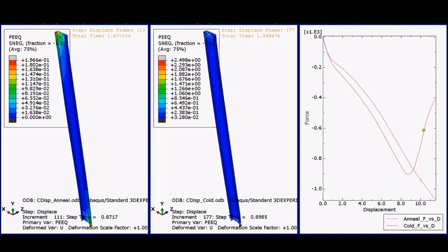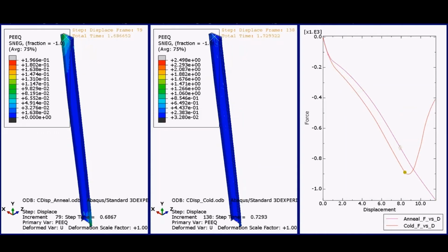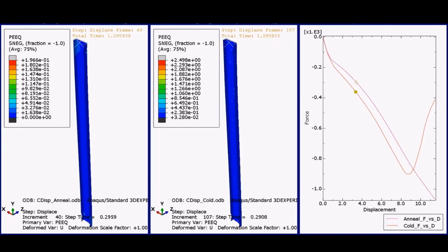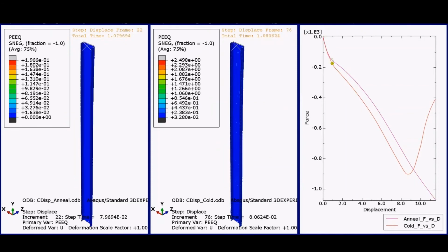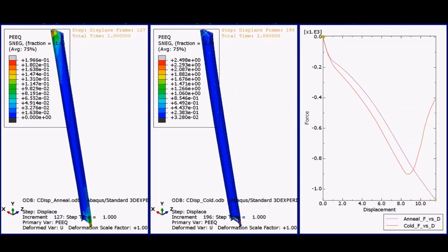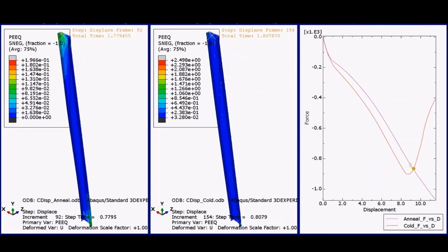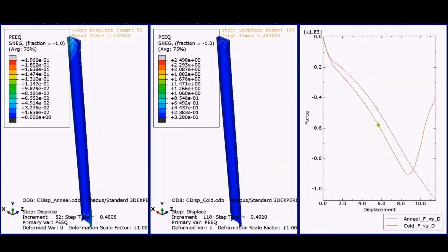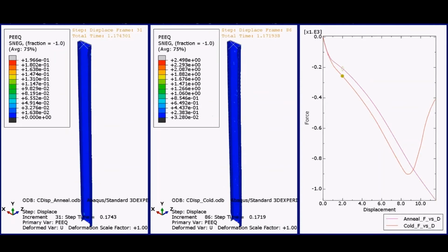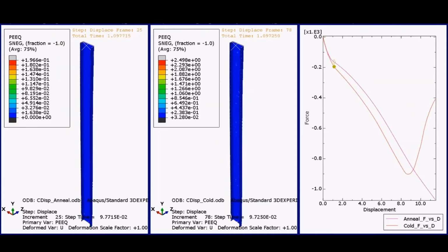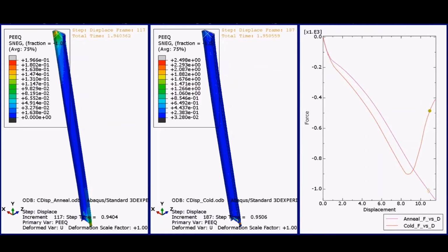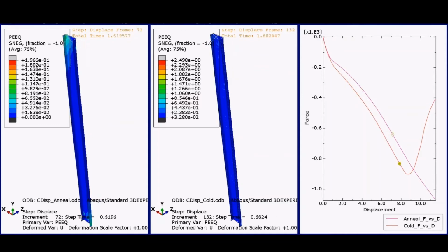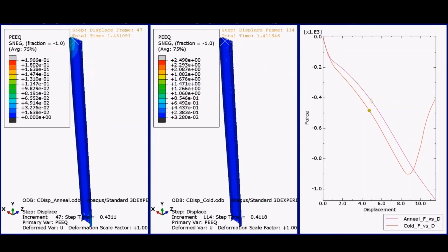The beam in the middle is not, so it starts with some strain hardening along the beam edges. And you can see there's a bit of a different response where if your priority is to get the maximum load, typically you'll have a peak displacement at a peak load, and you can take some fraction of that as your design load for, say, earthquake resistance. So in the case of the cold work beam, even though it reaches a lower peak before it has some local instabilities, if you take a fractional amount of that displacement and pick a load, typically it'll handle a higher force at any given displacement than the annealed beam, and so that one's actually better for a lot of applications.